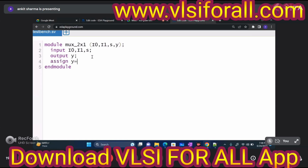And here I can say assign Y equals to S of, that means if the select line is 0, then it should have I of 1, and otherwise it should have I of 0. Don't worry about this. So this is the design. I should give appropriate inputs also to this design. The inputs I will also give through the tool only, which is a module PB. Don't worry about this name and syntax.